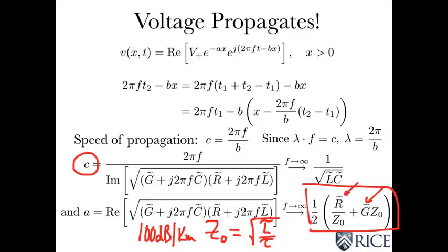So wireline channels have the problem that the signal can attenuate very rapidly. Now it turns out these equations also apply to optical fiber, and you'll find the attenuation factor is much smaller, and you can get 1 dB per kilometer or even less for very well designed optic cable, but for coaxial cable it's a different story.